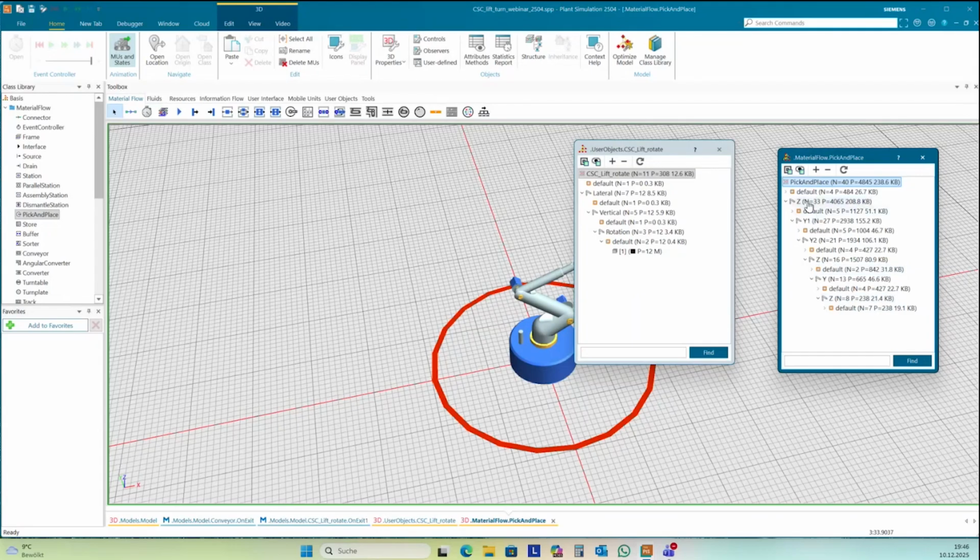Okay. If I give joints, automatically it will get it, right? Plant Simulation only supports a few configurations. You need to have the same axes in your robot: Z, Y, Y, Z, Y, Z. And if it's not this configuration, Plant Simulation will not be able to use your robot as a pick and place robot. It will not work. Yeah. In that case, we have to replace it with pick and place after giving the joints.